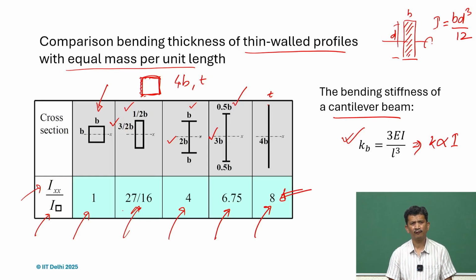So, if there is a bending load and we really want a very high stiffness, the ideal section should be just a thin sheet. We will call it flexures later; when we talk about flexures we will use that term, but for the time being it can simply be a thin section.